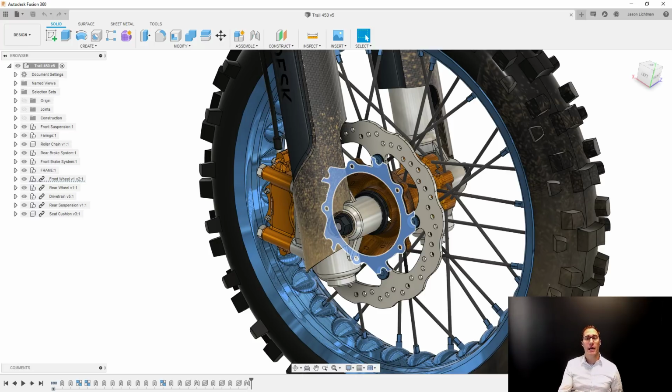So again, in this particular instance where I'm showing you that first method of reverse engineering, it's just to not reverse engineer it, just use it as the background. So you could bring an image from Photoshop into Illustrator, and then you could draw your vectors on top of that bitmap image. The same thing is true here. I could bring in my mesh into Fusion, and I could draw my BREP adapter plate to hold my disk on there. I could actually design that as a BREP while just using the mesh as a background.